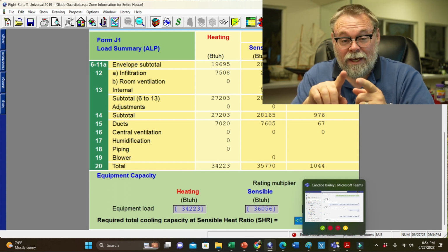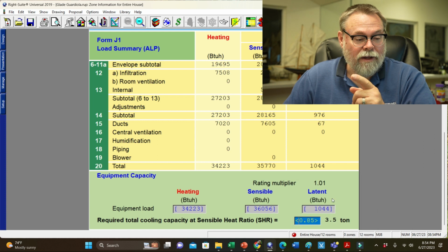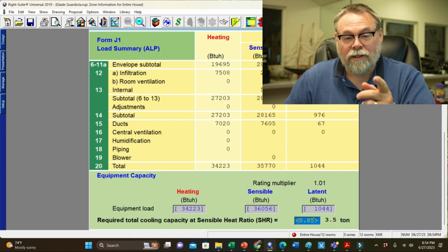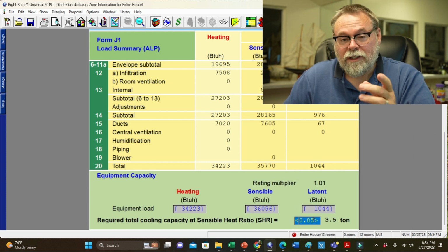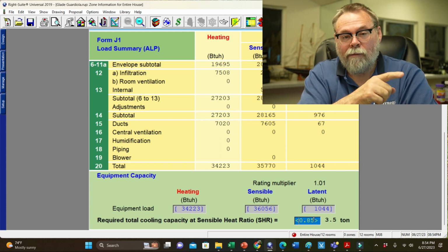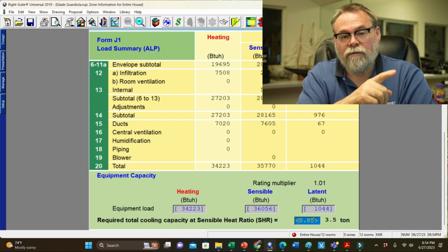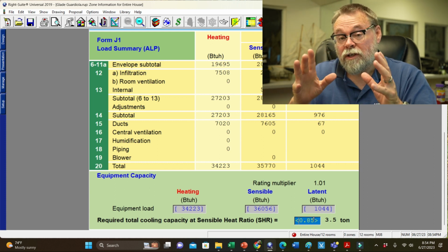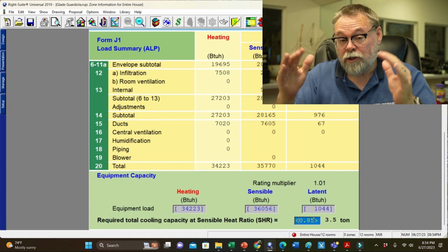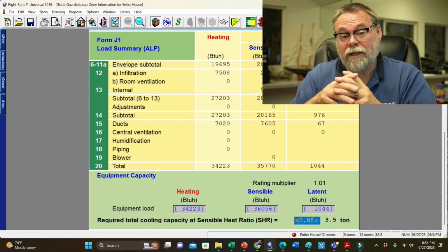You can see right there why we should do load calc on every system. We do not want to just swap boxes. Swapping out boxes creates problems. Now, her ductwork is designed for 4 tons of cooling, so her ductwork's oversized. If we put it in there, her static pressure should come down to be really nice on this house.